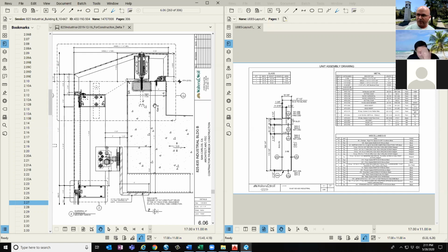So all of those things may factor in when I'm actually doing the check on this unit. For now, I'm still identifying what's happening with the unit itself. So far, what I've determined is that it is a sill track at the bottom and a parapet head. So that gives me the guidelines of what type of framing this unit is built out of.